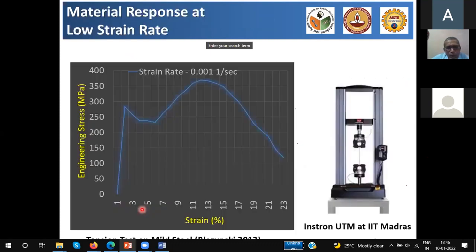So now when you look at the stress strain curve, which is what we ask all our undergraduates to plot in their strength of materials labs, you will expect them to generate some curves of this type, where you plot the engineering stress against what you measure as strain. You can convert the strain into nominal strain and convert the engineering stress into true stress and get these responses.